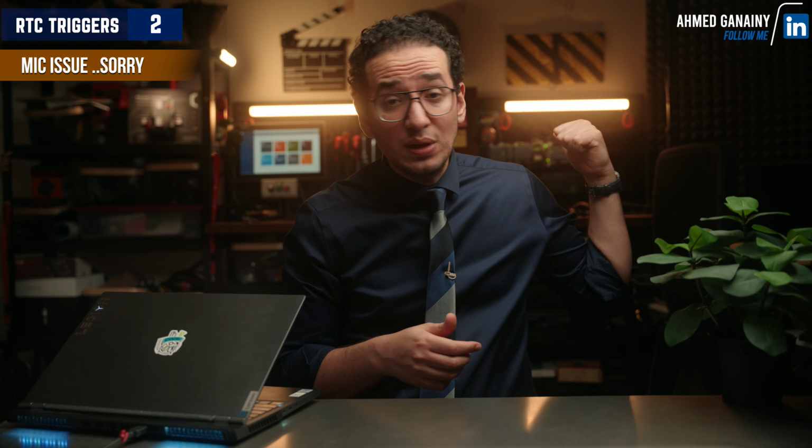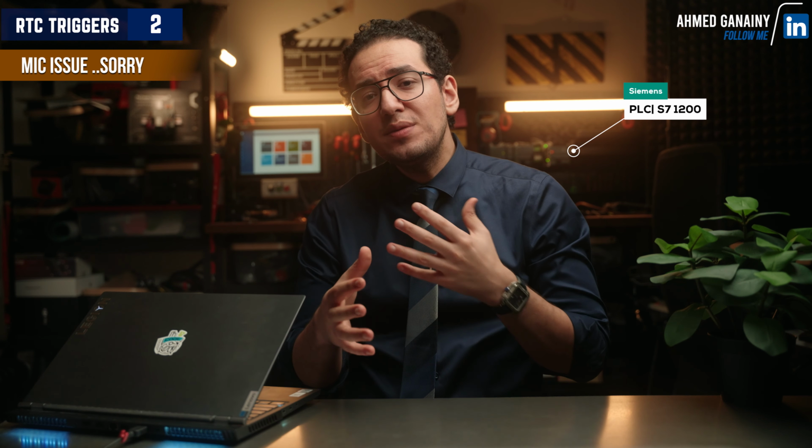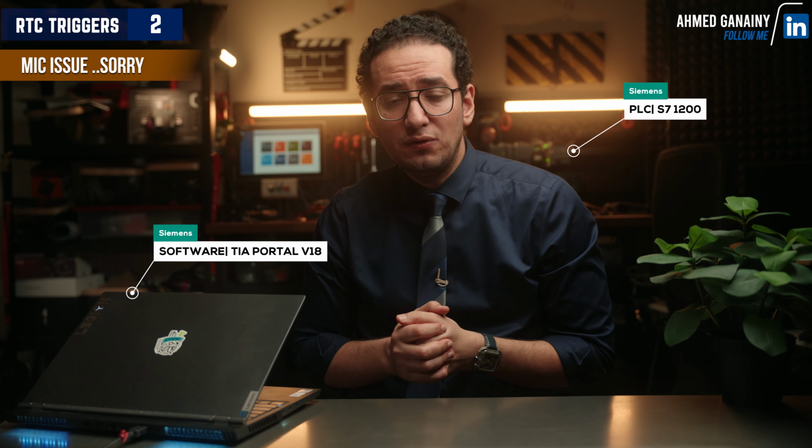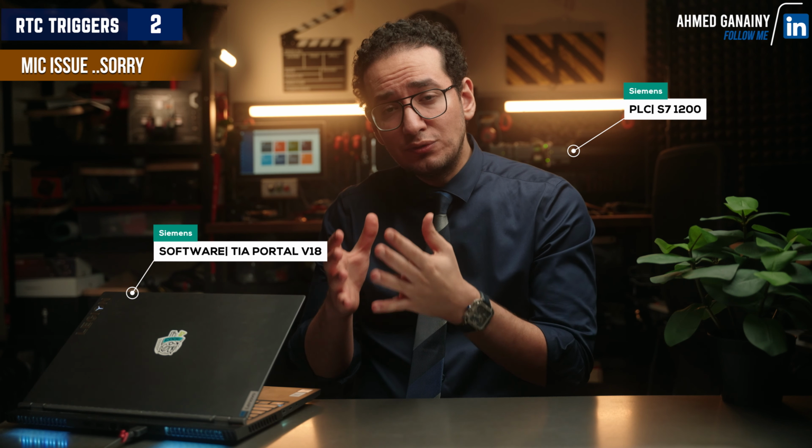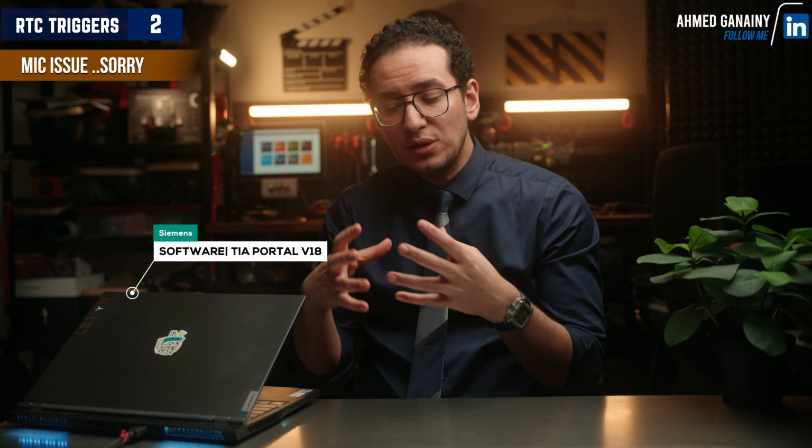Today, we'll take an example of one-day triggers, which is a very common practice to send your flow totalizers, number of starts, number of faults, asset utilization, which will definitely help you in the next level for performing statistical analysis or even OEE calculations. Today I'm using the S7-1200 and the TIA Portal, and the same concept will be applied to any other PLC or software. The only difference is how to read the real-time clock. Some PLCs will give you access to read and write through the RTC blocks, and others through system memory words. So let us move to this example.